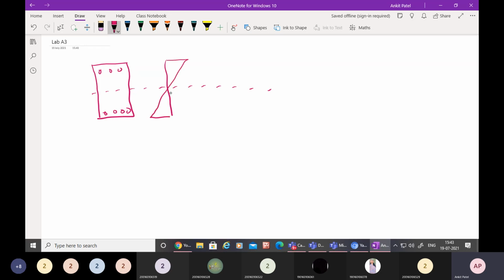So first of all I'm going to draw the strain diagram. The maximum strain carrying capacity of your concrete is 0.0035, and from this side you can find out the value of strain with the help of the equation epsilon SC equals 0.0035 (1 minus d' divided by xu). With the help of this equation you can determine the strain of concrete at the level of reinforcement. So this is the level of reinforcement. Now if you draw the stress diagram, it will look like this.